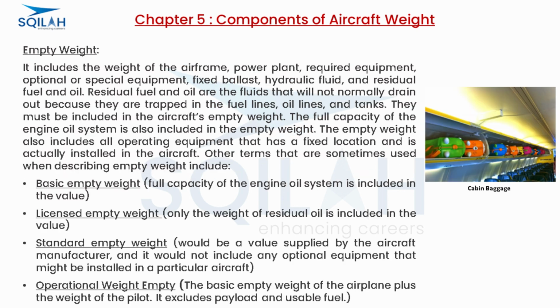Empty weight. It includes the weight of the airframe, power plant, required equipment, optional or special equipment, fixed ballast, hydraulic fluid, and residual fuel and oil. Residual fuel and oil are the fluids that will not normally drain out because they are trapped in the fuel lines, oil lines, and tanks. They must be included in the aircraft's empty weight.